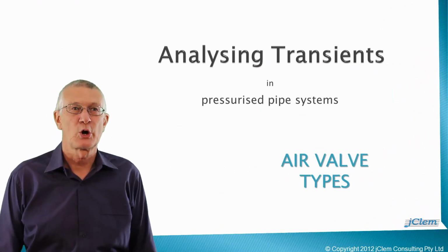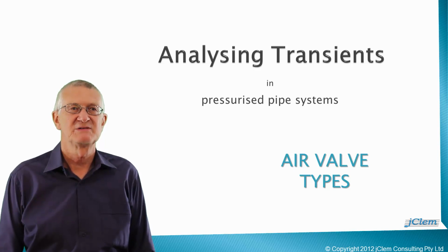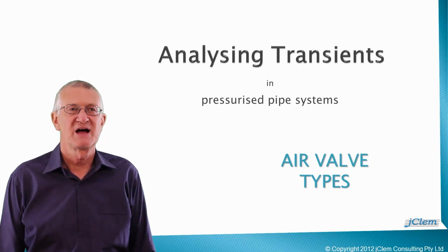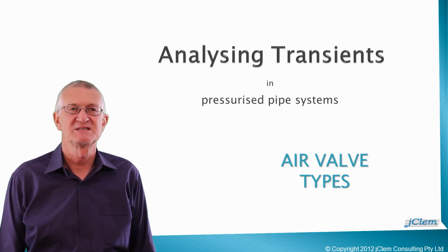Welcome to this lesson on air valves. Air valves have the potential to be an effective and inexpensive form of surge protection when used in the right situations. Today, valve suppliers offer a wide range of air valves, some of them designed for special situations. As a result, engineers need a solid understanding of air valve basics and how the operation of air valves is related to transient analysis and surge protection of pipelines.